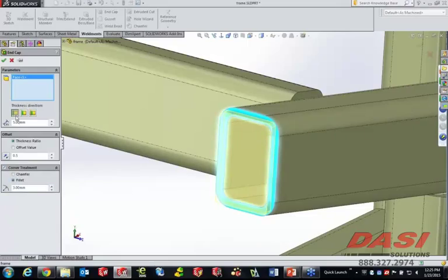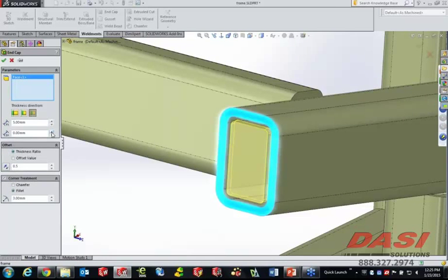But I can change this from an end cap, which is actually outward, to an end cap that is inward. We've had those before, flush to the outside face, but this is now a recessed one we call internal. Internal allows you to push that value back into the part as well. You can see it moving into the part. And I'm just going to put that in there 10 millimeters with a really, really minor offset here, because I want you to see what this looks like.